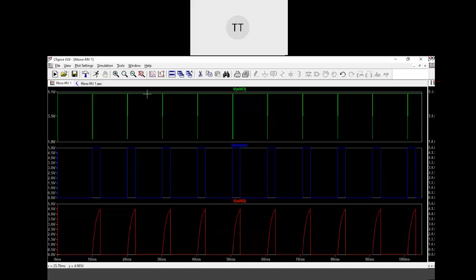Just put it in a box, all of you. That's why in one of my assignment questions I asked, what do you mean by a valid trigger signal for a 555 timer? One of the things is that a valid trigger signal for a 555 timer is one whose low value should be lesser than VTL of that particular circuit.